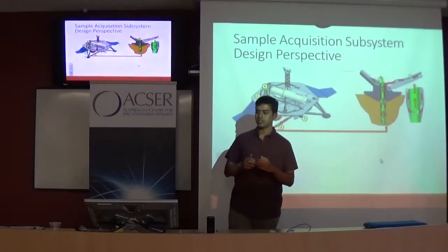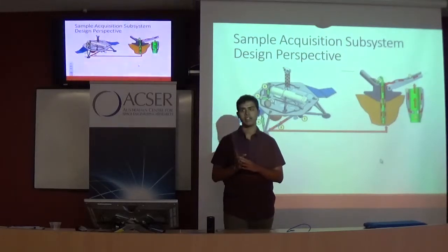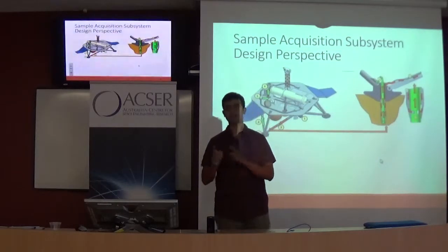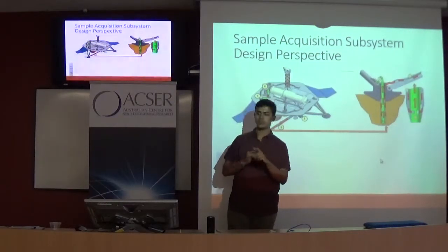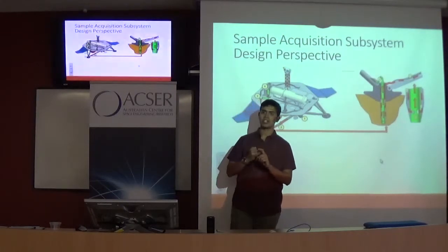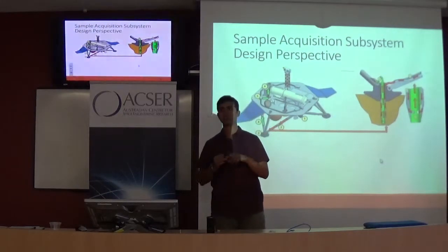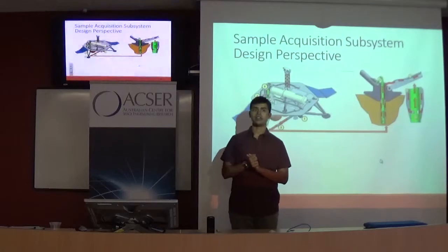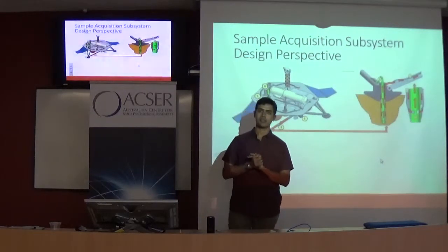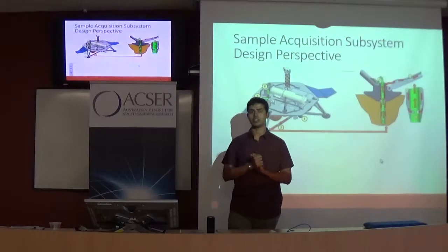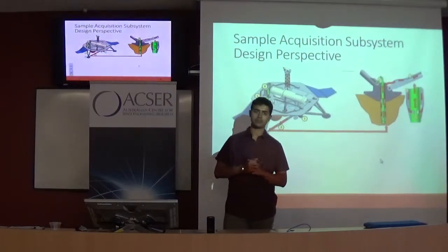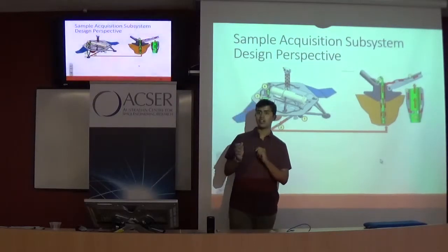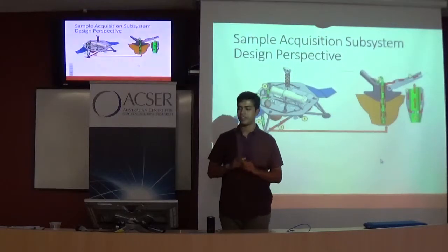But as a researcher, I was actually interested in understanding how this pressurized gas would interact with the regolith in a reduced gravity environment. The objective for this work, of course, was sample acquisition. But ultimately, when you're trying to do in situ resource utilization on Mars or on the Moon or elsewhere, pneumatics is one of the biggest. The advantage is that you're not having any actuators, you're not carrying that extra mass of different heavy actuators.